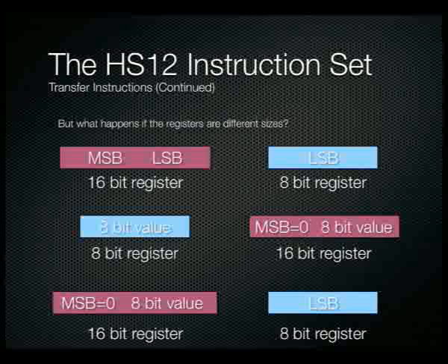So yet again, like I said before, you need to check to ensure that when you do an exchange or a transfer from a 16-bit register, you ensure that the value in that 16-bit register is less than or equal to 255. Otherwise, it's just going to cause a random sort of value being transferred for you, or an incorrect value at least.